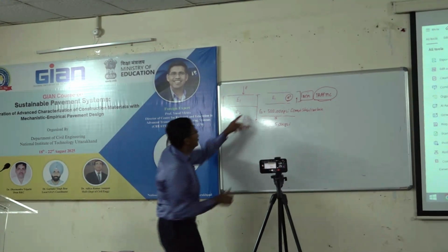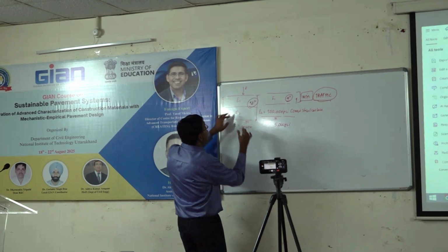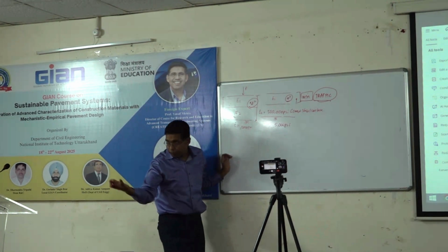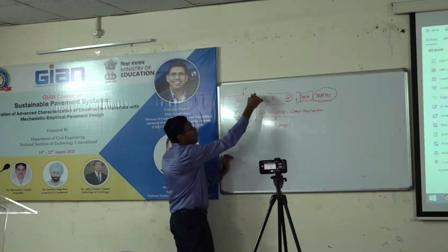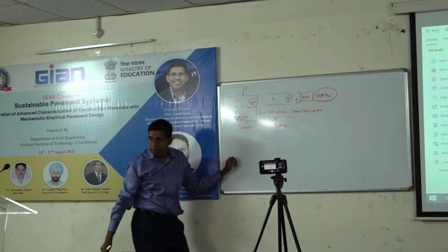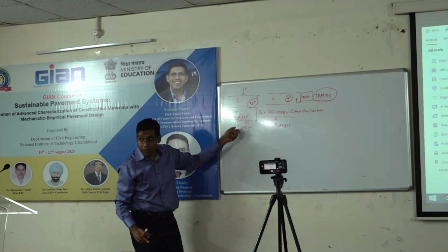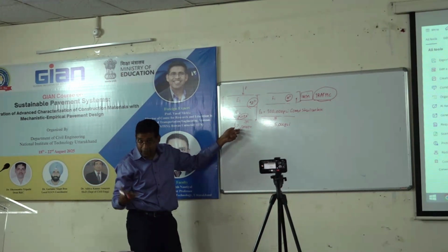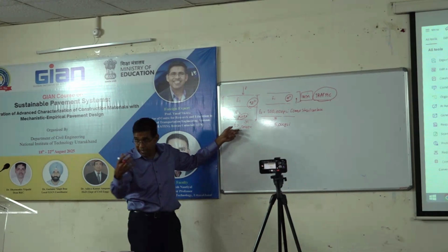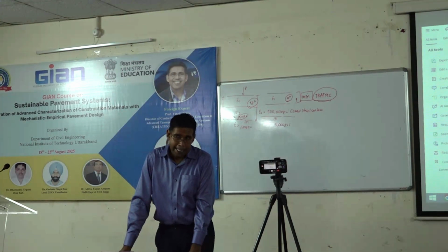So if I lock you to 50 inches, right, and you provide a very weak subgrade trying to save money, let's say 10,000, you will end up having 60 inches. Can everybody understand that? That means I have to excavate how much? 10 inches. Correct? I have to excavate 10. That's a cost. I have to take the material out, I have to haul it, and so on and so on. Questions?